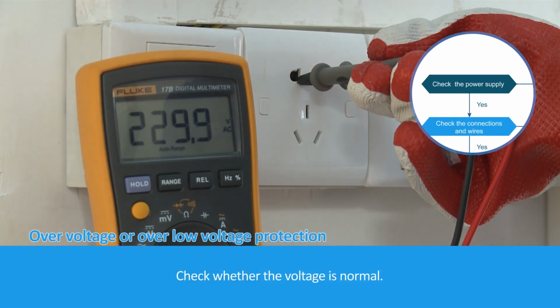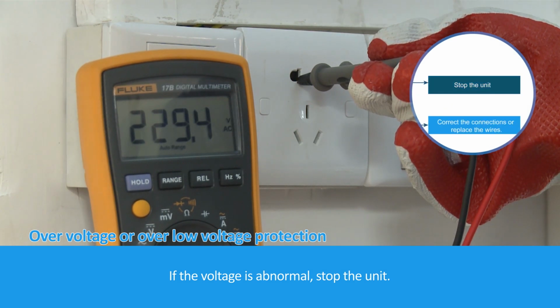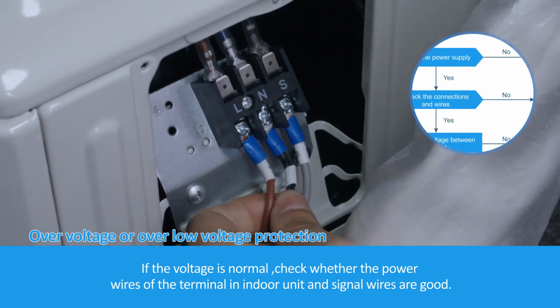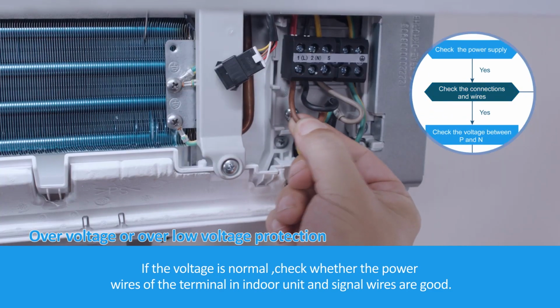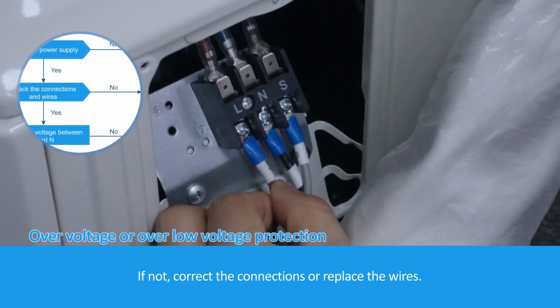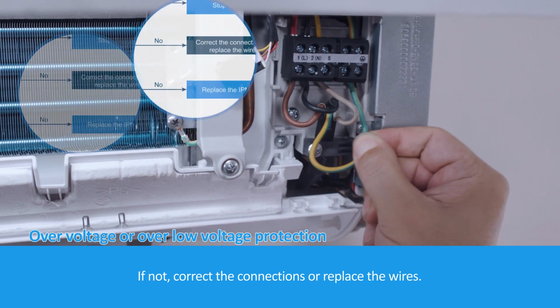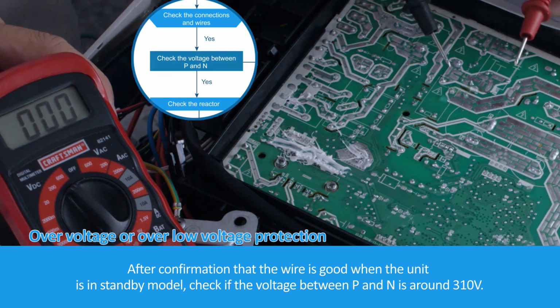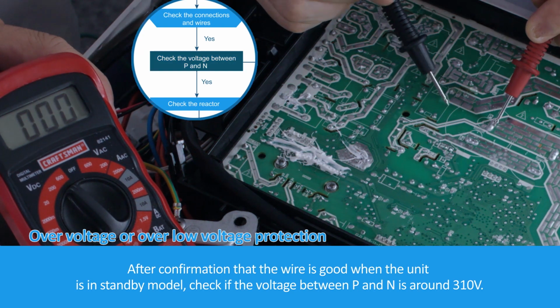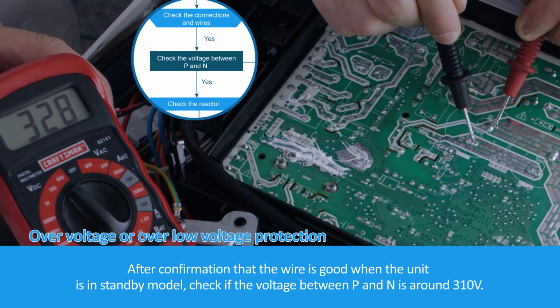Check whether the voltage is normal. If the voltage is abnormal, stop the unit. If the voltage is normal, check whether the power wires of the terminal in the indoor unit and signal wires are good. If not, correct the connections or replace the wires. After confirming that the wires are good, when the unit is in standby mode, check if the voltage between P and N is around 310 volts.